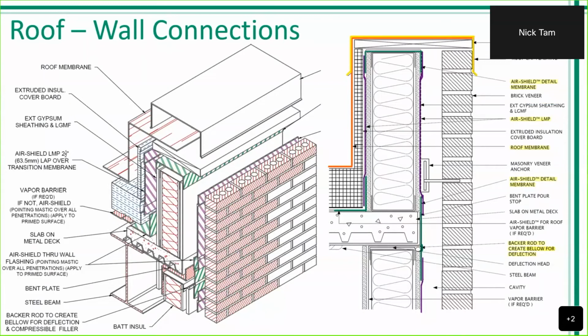That concrete beam meeting the edge there is being treated with a transition membrane from the wall going over the entire concrete slab, going to the other side of the wall, and we're treating the edges of it, keeping it monolithic. We also have the roofing membrane actually encapsulating the very top, and we're making sure that we prevent any moisture creep from underneath. So this is a good example of good segmentation, but do know that there are a lot of different methods that can be used to create a good encapsulation of our structure.